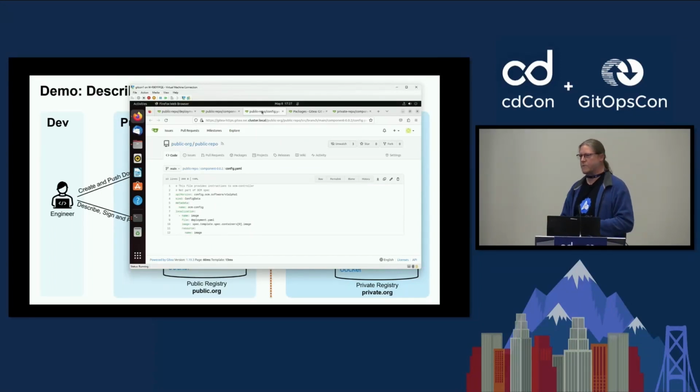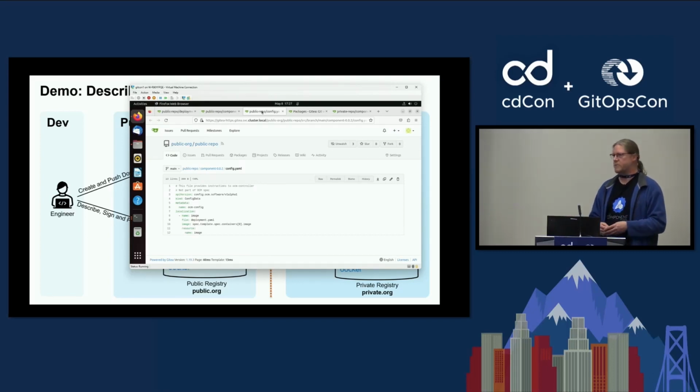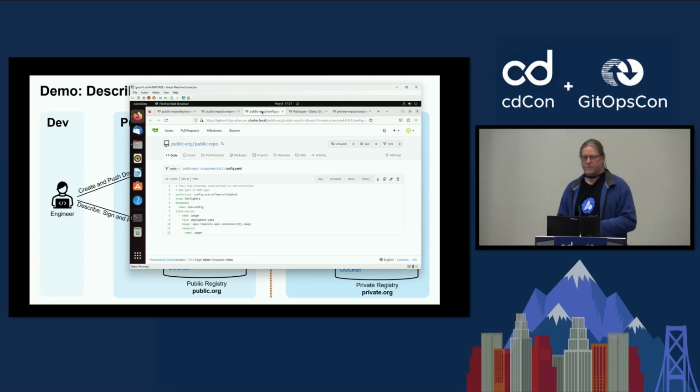Here we're talking about deploying with Flux, so Helm or Kustomize. But OCM is extensible, so you could be working with RPMs or whatever other stuff instead, in which case the rules would be different. So for this file, this is something that is going to be looked at by the OCM controller, this resource. And it's going to tell the OCM controller some information it needs in order to perform the localization. So we have here what's going to be localized, deployment YAML, what part of that YAML is going to be localized. You can see the path there. And then what's going to happen is whatever the location of the image is for this component, that's going to be fed into that value.